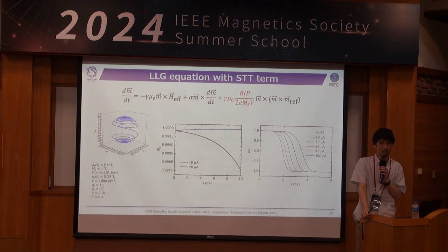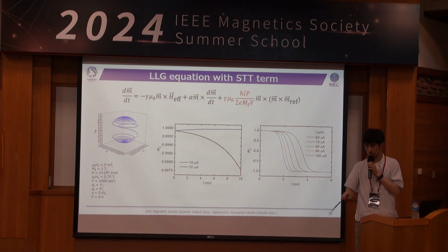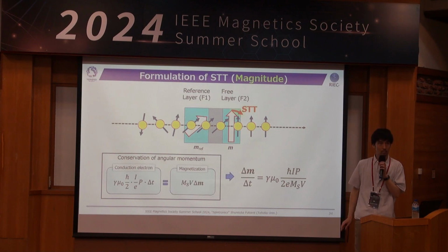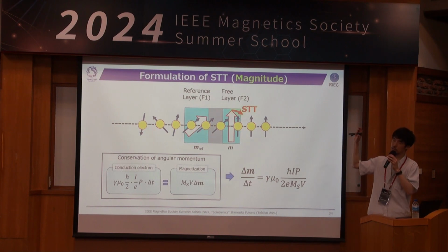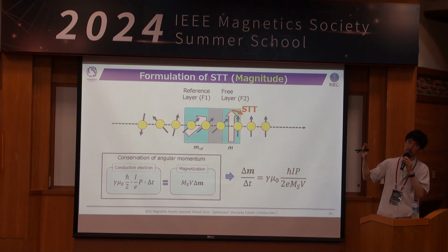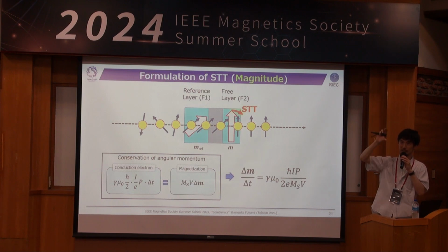So in this case, for example, if we want to use low power to protect our device and also save energy, what level of pulse can you use to switch the magnetization? Can it be sub-nanosecond or even a few picoseconds? As far as I know, sub-nanosecond switching was achieved, probably first, by IBM. They showed sub-nanosecond switching by the MTJ, but the stack structure is special. If I remember correctly, they had two layers sandwiching the free layer, in which double spin transfer torque is expected.